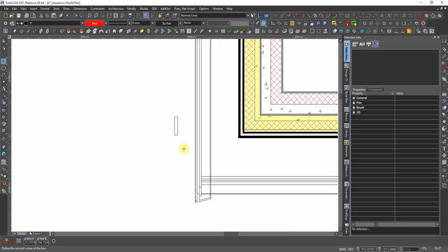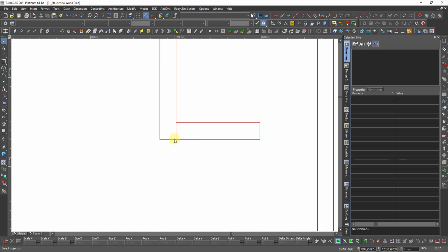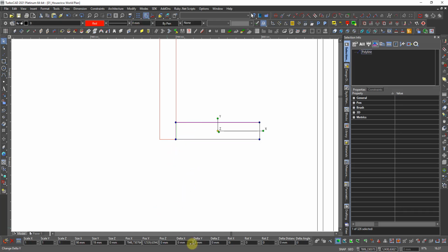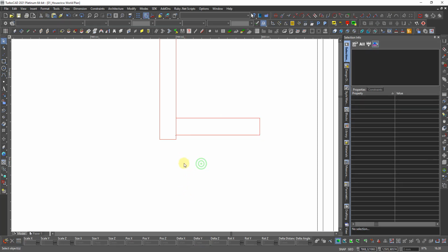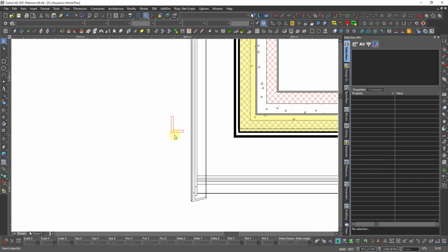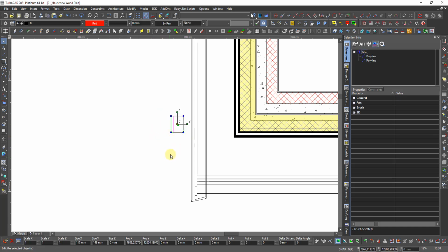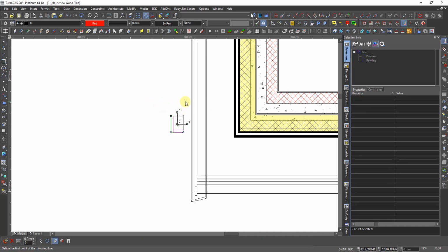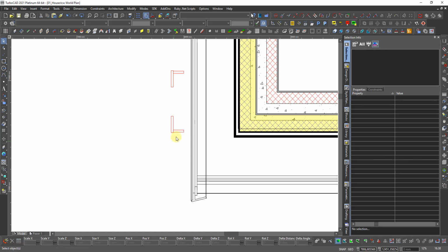rectangle. The front I want to be 6 inch, that's 19 by 148. 19, 148. And I want one that is from here, that is like 1 inch smaller, so that would be 98. So then it should be 98 by 19. And because in the real world we never make this look nice, so I move this, I don't know, 5 millimeter, and I need to make a copy also, because we have right side and left side. So I rotate about this point, pressing shift, and then I have left side and right side.